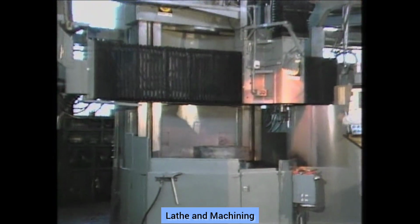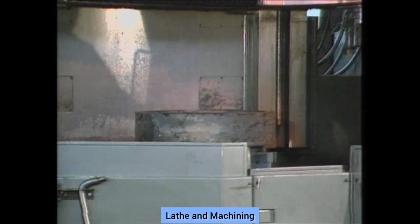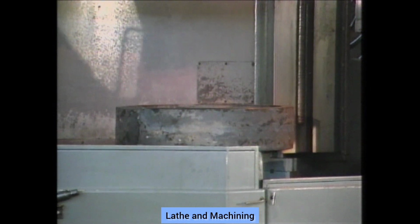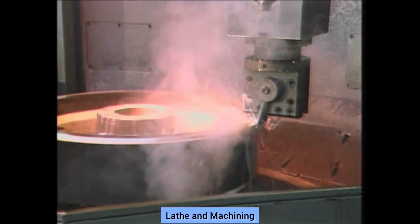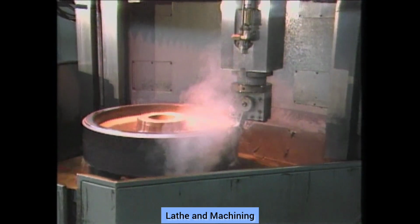Vertical turret lathes, or VTLs, are commonly used for large diameter round parts, not suitable for holding in the chuck of a horizontal lathe. The work is clamped on a rotating table 2 to 6 feet in diameter. Tools in tool blocks or turrets may be fed from above or from the side into the rotating work.